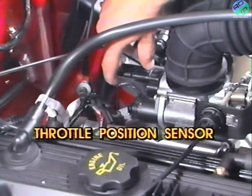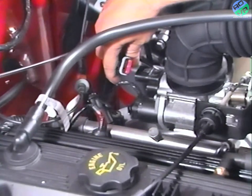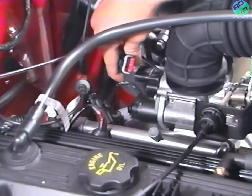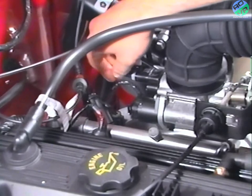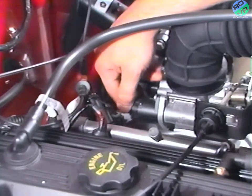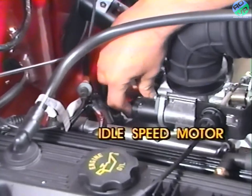Check the throttle position sensor electrical connector. This is especially important if the vehicle has been worked on recently. The TPS connector only goes on one way. Check the output connections in the same way, such as the connections on the idle speed motor.